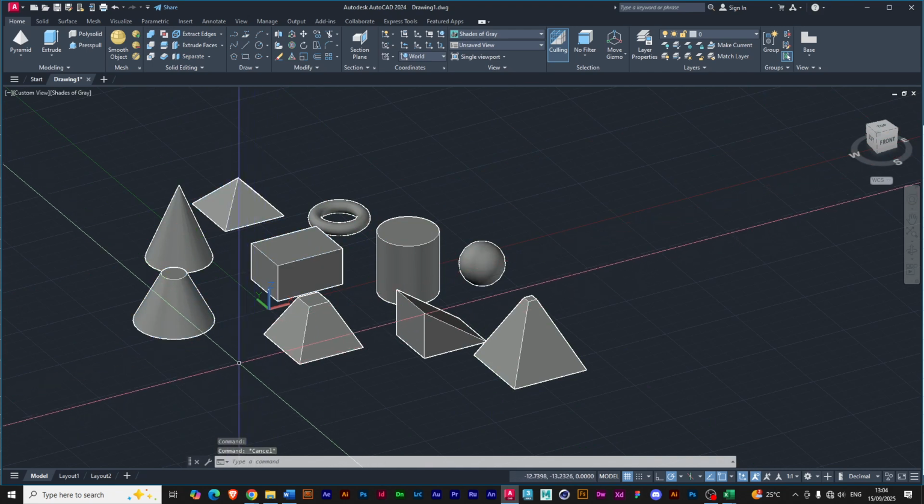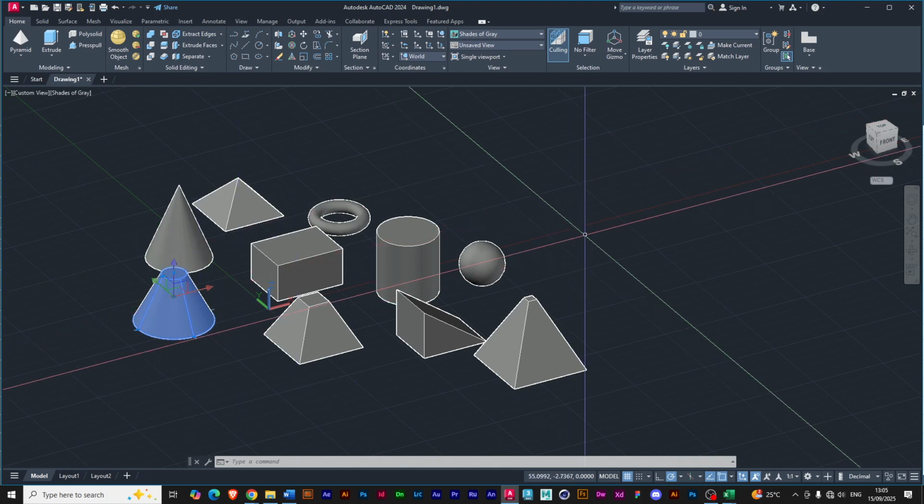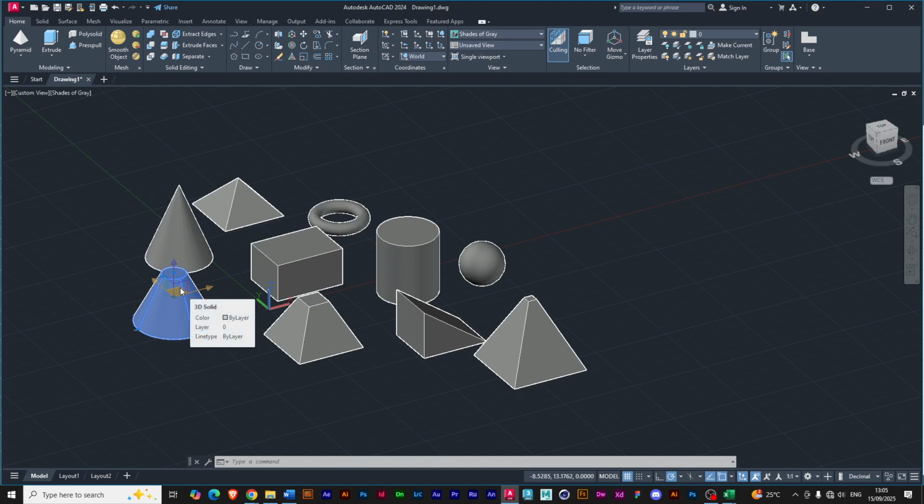But now, to move, when you click, AutoCAD is not a drag and drop kind of software. Like in Illustrator or Photoshop, you select an object, you click and drag to drop it somewhere. Like now, I want to move this guy here. So I already have my axis handles and I have my axis bands. Remember, the axis bands are like axis planes when we're doing 3D, and I showed you what those mean.